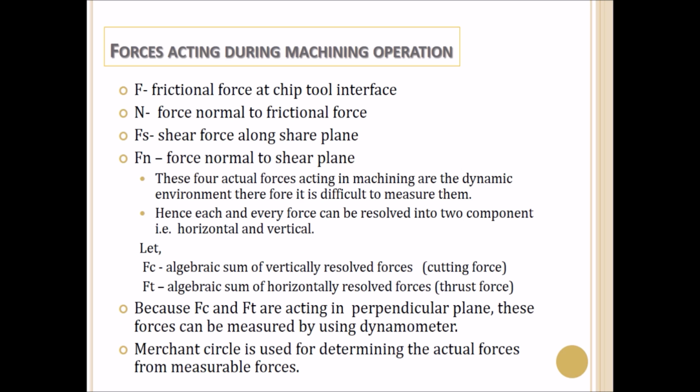So forces acting during machining operation. Let us consider a machining operation in which a single point cutting tool is used to machine a workpiece. While machining, different kinds of forces are generated. Due to friction, there is a frictional force at the chip tool interface. Then there is a shear force which acts along the shear plane.